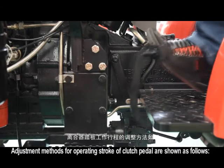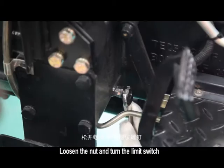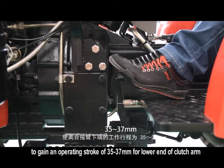Adjustment methods for operating stroke of the clutch pedal are shown as follows. Loosen the nut and turn the limit switch to gain an operating stroke of 35 to 37 mm for the lower end of the clutch arm.